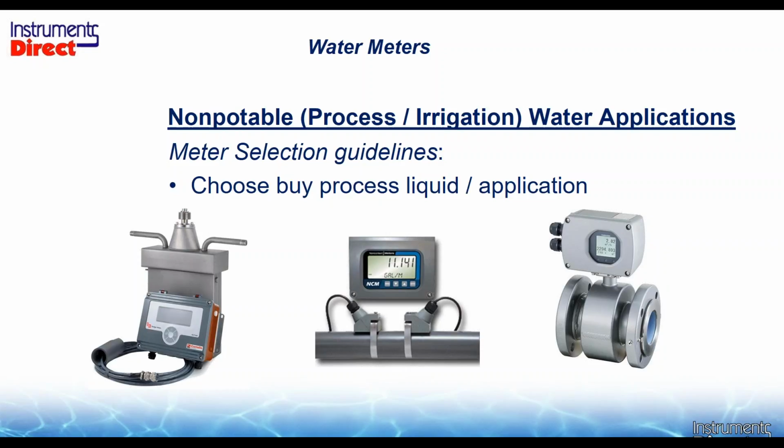Ultrasonic flow meter in the center here, this is traditionally a 1% application for most clean liquid applications. And over to the right here, this is more accurate. We're down to 0.3% or 0.25% with a traditional magnetic flow meter. Very accurate technology, reads a little bit lower flow rate than the ultrasonics there, a little more accurate. It costs more, so we picked that for those specific reasons there.